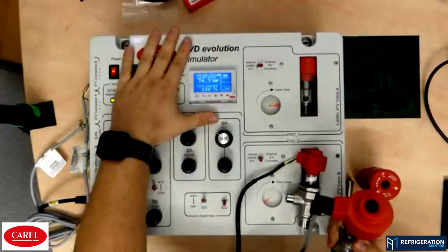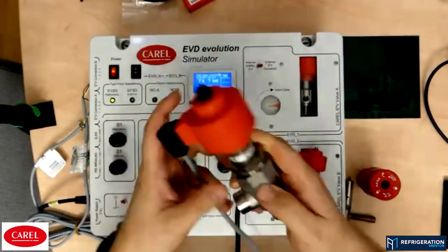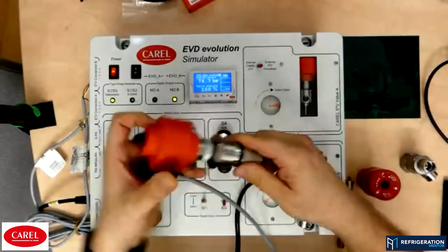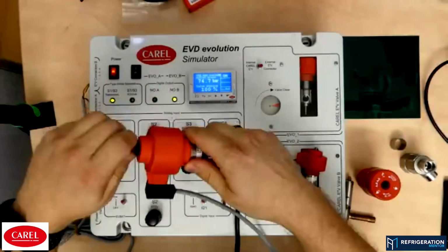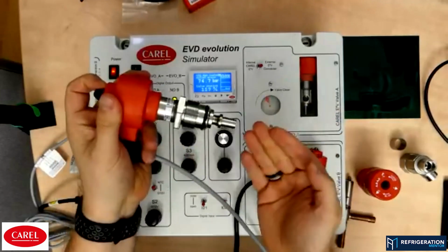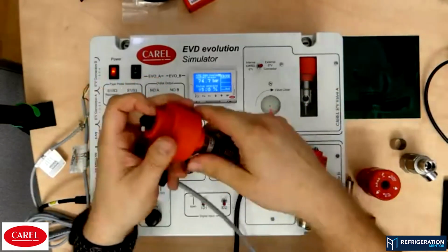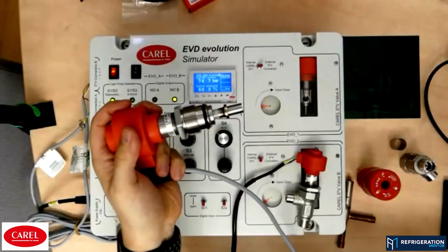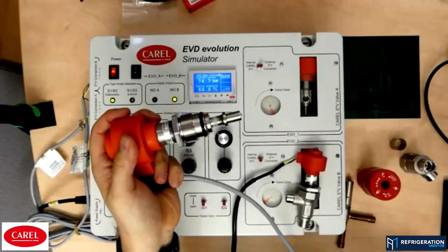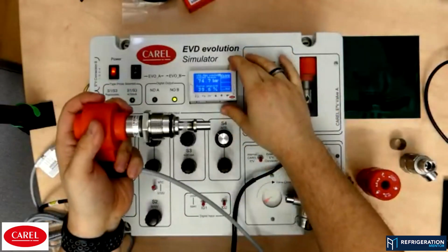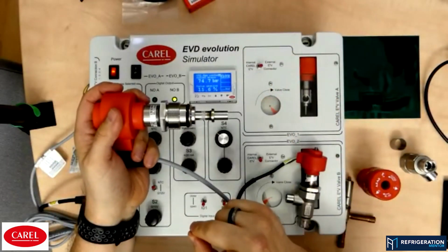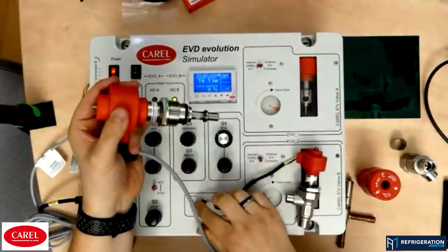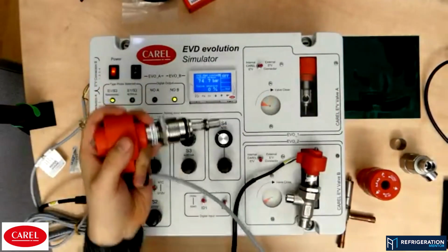This is a standard expansion valve driver, EVD evolution. I have connected here my HPV valve. Let's open this valve. And now I will start the regulation, and we will see the valve is opening at the moment, how it should work. So that's great. So keep in mind, we have a valve that's only open by the minimum percentage. Our controller has no idea what the valve is really doing. When I disconnect our data from our actuator, so from the valve body, so to speak, it will have no idea where it is. And exactly this was the problem.